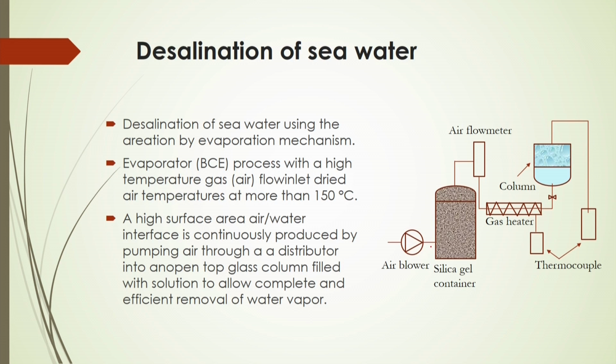Another important application of this two phase bubbly system is desalination of sea water. You have to remove the salt from the sea water, so you have to evaporate the water by bubbling systems. In this case, in the bubbling evaporation process, inlet dried air at a high temperature of more than 150 degrees centigrade is supplied through the liquid medium.